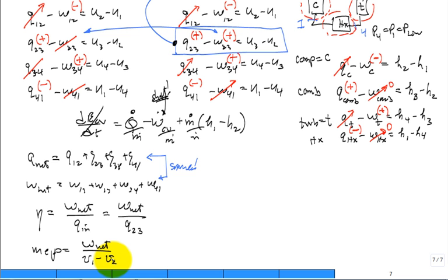So you just take the total, let's say a 5 liter engine, 5 liters and 8 cylinders. 5 divided by 8, whatever that gives you, is how many liters per cylinder. That's the displacement volume, the swept volume as it moves from bottom dead to top dead center. That's a metric you can use to compute the mean effective pressure. Usually you like a high mean effective pressure for a lot of work out for the same displacement volume. But again, the thermal efficiency is good.